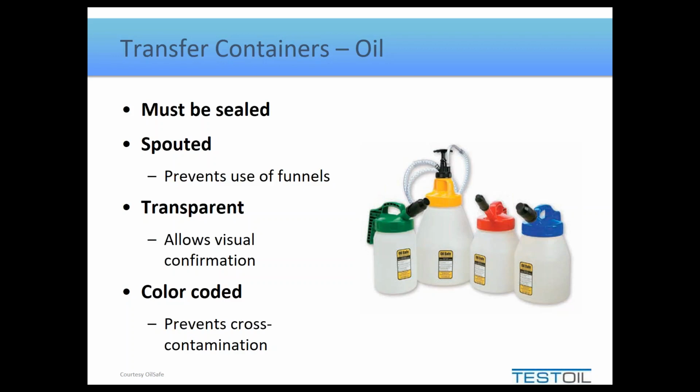It should be noted that most of these oil-safe type containers, they do have color-coded lids, but they also have color-coded collars on the bottle. So that's what allows you to get more combinations than simply the 5 colors that they typically offer. You can now add in 5 other colors of collars, so basically you've expanded your number of lubricant choices up to about 25.